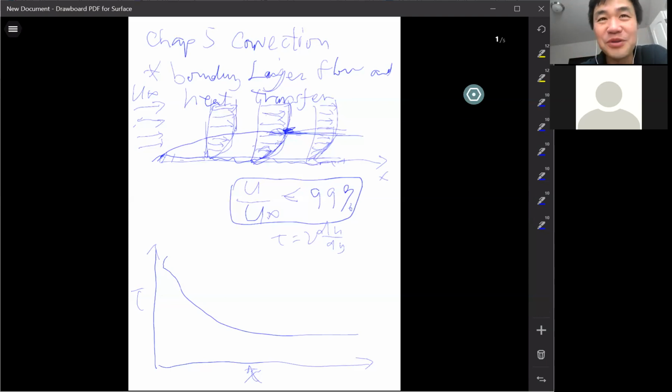Okay, pressure drop is not good, right? Do you know that? It matters in most engineering applications, for example, in pipe flow. In a heat exchanger, you want to enhance the heat transfer from the pipe to the flow. Usually when we enhance the heat transfer, automatically the shear stress will increase. Shear stress is related to the pressure drop.